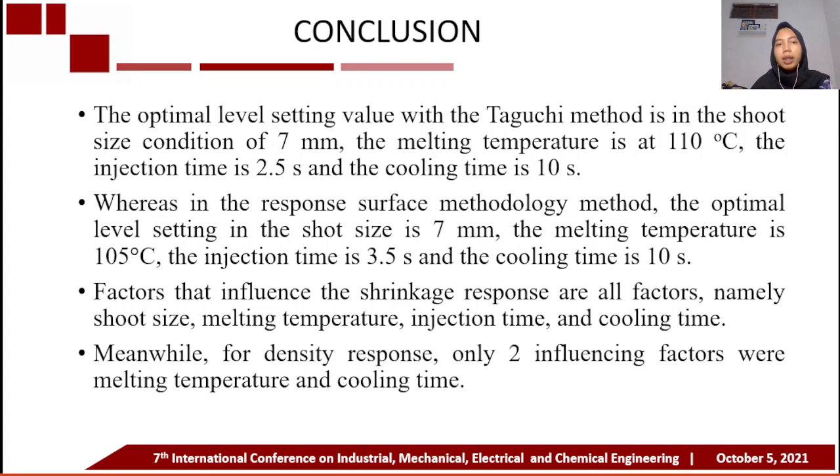And the last is conclusion. There are 4 conclusions. The first is that the optimal level setting value with the Taguchi method is a shot size of 7 mm. The melting temperature is 110 degrees Celsius. The injection time is 2.5 seconds and the cooling time is 10 seconds.